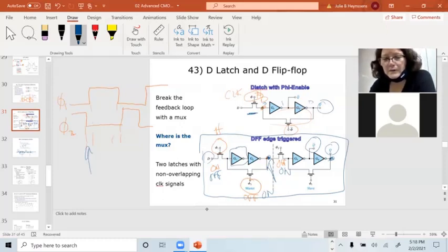It's acting as a buffer. You could just put a straight wire between there, but with 2 inverters, you've got a buffer, so it gives you better signal strength on the output. Okay, I think I understand this now. Thank you so much. Usually, if you want to buffer something in a digital circuit, you use 2 inverters, because it's hard to get positive logic.